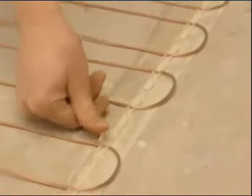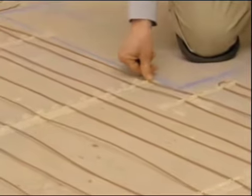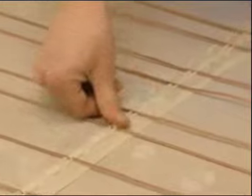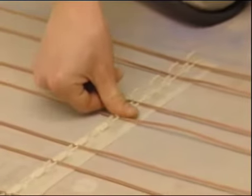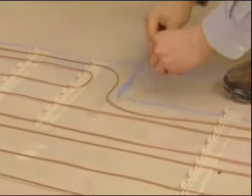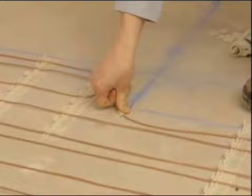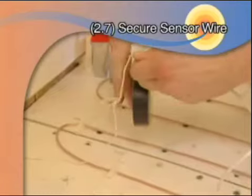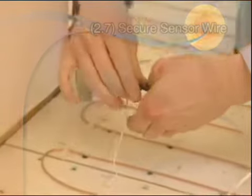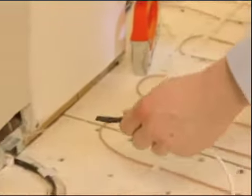Once the cable layout is completed, close all hinged clips, including the hinged clips not used, to securely fasten the cable to the floor and flatten the height of the system prior to application of the thinset. Use additional clips provided to fasten down any part of the cable that is not snug to the floor. Next, secure with electrical tape the pigtail end of the warm tiles thermostat sensor wire to the second pull cord and pull into the junction box.